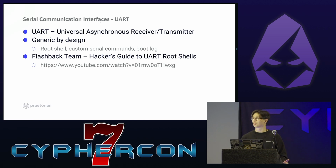Awesome. That's in a lot of the intro to IoT hacking videos you might find on YouTube, where it's: find the UART interface, connect to it, root shell, profit. But sometimes it's a custom interface for proprietary serial commands. Sometimes it's just a boot log. Sometimes it's really just startup information. So what you get varies, but certainly if you see something that looks like a UART interface, it's worth taking